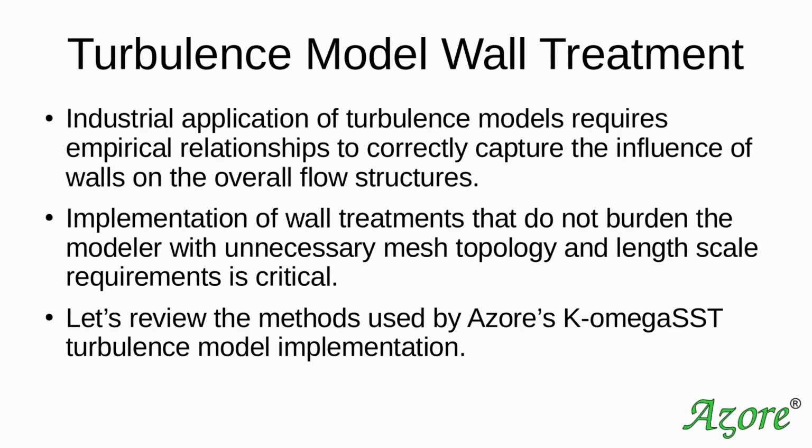Some people think that if you implement a turbulence model, you're going to get it perfect. It's going to be accurate. And in order to use this turbulence model, you have to have a y plus of 1. We're going to talk about y plus in a moment. But that really hamstrings the person who's putting the mesh together. It's basically saying you need a really, really fine mesh everywhere. But that's going to be hard because you don't really know the flow structure around it.